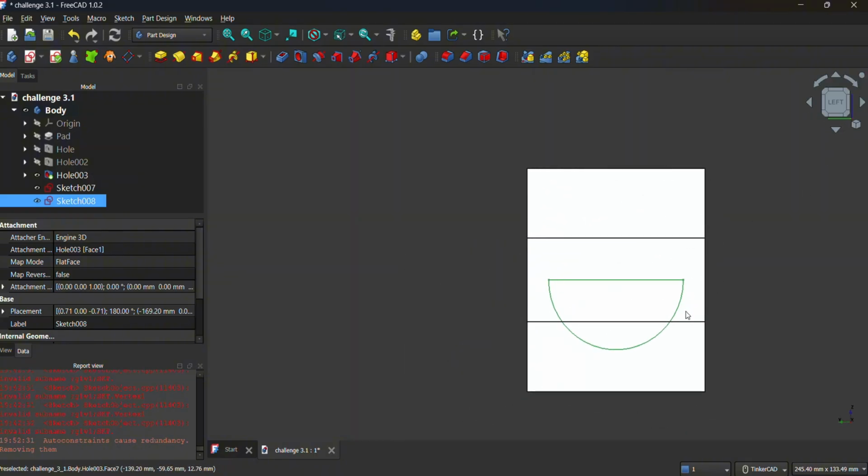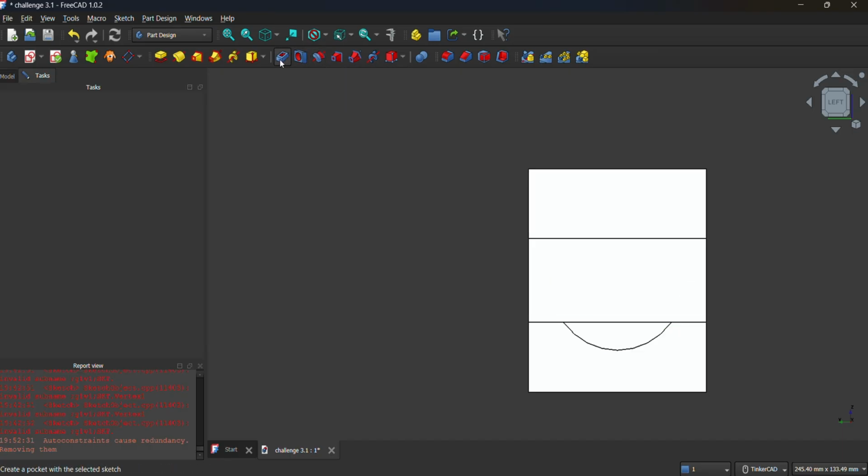For you to see clearly, this is the one that we have drawn. From the top view, of course, it's just a rectangle, and in the side view, it's a rectangle. But in this side, which unfortunately is not shown in the technical drawing that we have as a guide, it's actually curved. Because there's already a note that there is a radius, you will conclude that it's an arc. Now we can create a pocket, not a hole, but a pocket.